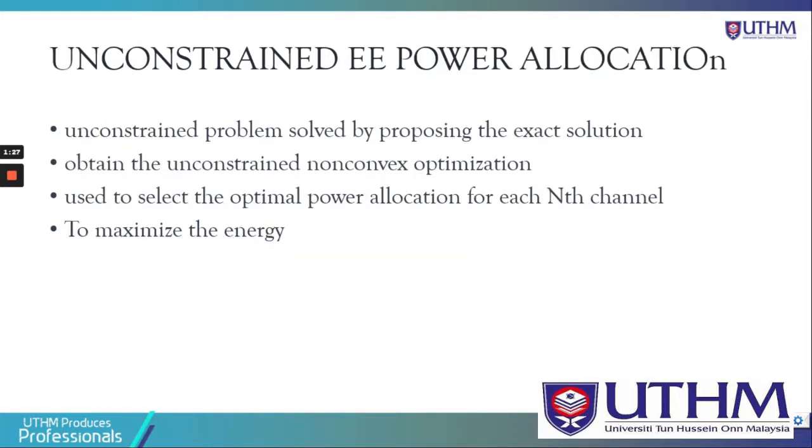Okay, the last one is the unconstrained energy efficiency power allocation. The unconstrained problem can be solved by proposing the exact solution to the unconstrained non-convex optimization problem, used to select the optimal power allocation for each channel to maximize the energy efficiency.